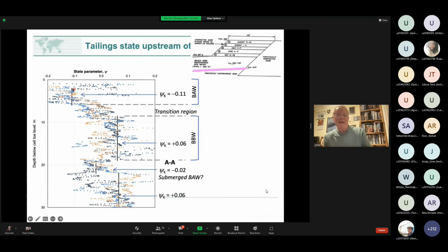And you can see, we've allowed one or two bits a little bit looser than we think. By the way, I should say dense is over the left, loose is over on the right. So we're honoring that, and clearly down here, which is much looser ground, there's a harder layer in here, and there's a layer down the bottom. So that's what we came up with. That's how we did our characterization.